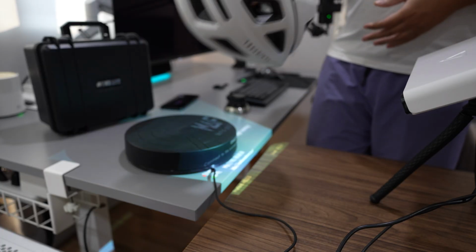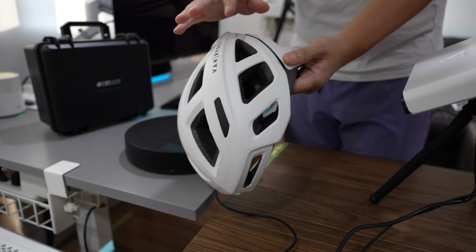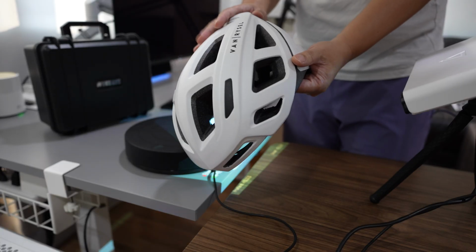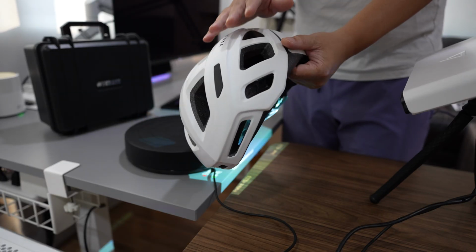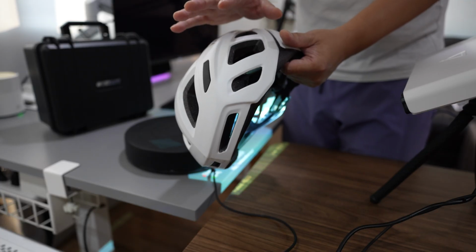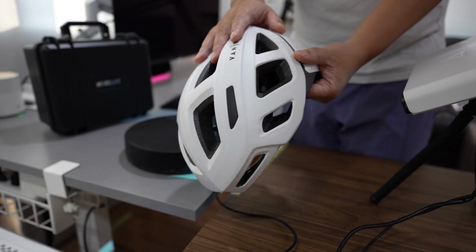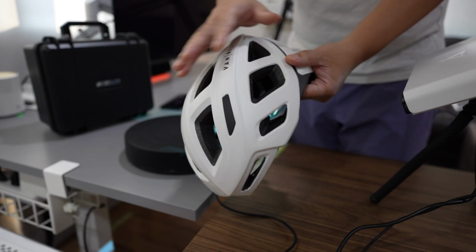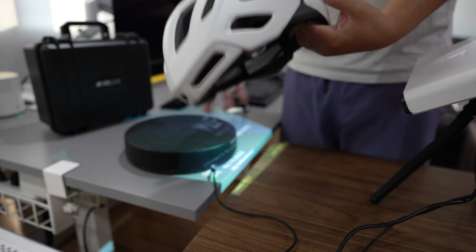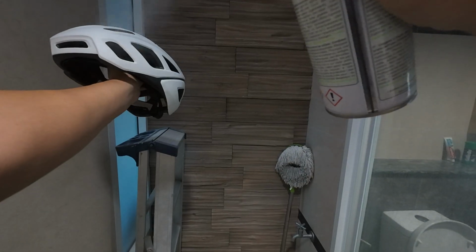Okay, before I start 3D scanning, this object has a white color and also the black color of the foam, so it's a very high-contrast color. So I will spray the black part so that it will be captured together with the white color of the shell. Because this helmet is water washable, I can wash it after I make a 3D scan, so I can spray. And okay, let's start with the spraying.